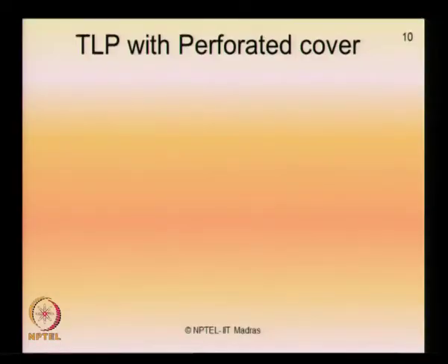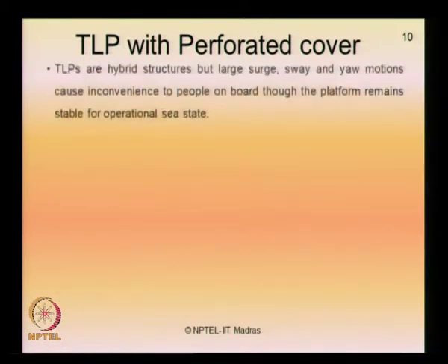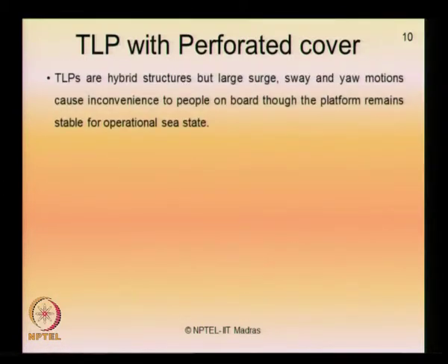Now, as an example of this application extended on a marine structure, a tension leg platform with members with an outer perforated cover has been attempted experimentally and numerically. We all understand that TLPs are hybrid structures. They have very large surge, sway and yaw motions, which cause inconvenience to people on board, which we do not want.